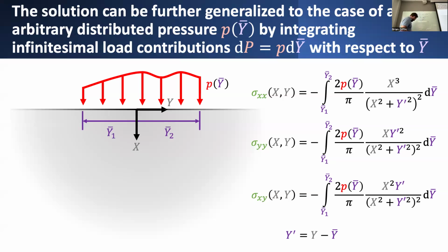So yeah, in general, I think there's a couple different ways you could do it. There's this assumption that, let's say you had a truly three-dimensional problem rather than a two-dimensional plane problem where we're looking at a plate. Now imagine that this is viewed in profile, an actual three-dimensional domain. Below this line is the interior of the earth or the soil, and maybe you have a building sitting on top of this. And you can idealize the distribution of load applied over the footprint of this building.